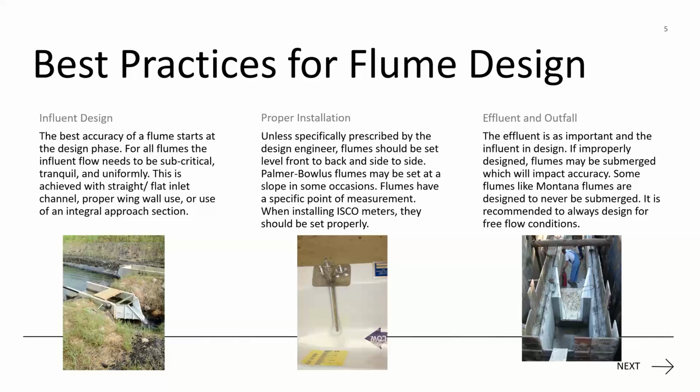If they are submerged, you'll automatically just lose all of your accuracy. So it's important, when designing, to just go ahead and design for free flow conditions. That way you avoid any of those downfalls of submerged flow.